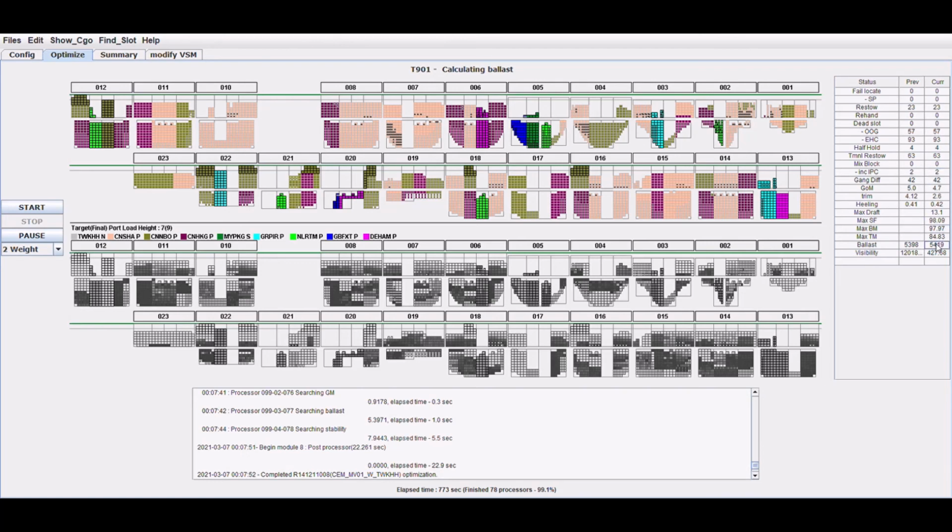According to the Kaohsiung stowage optimization results, all cargoes were assigned to a slot location without rehandling, and the ship's departure GM, trim, and various stability indicators were also satisfied, within an appropriate range. The stowage plan currently displayed on the top main screen will be the final Kaohsiung bay plan.